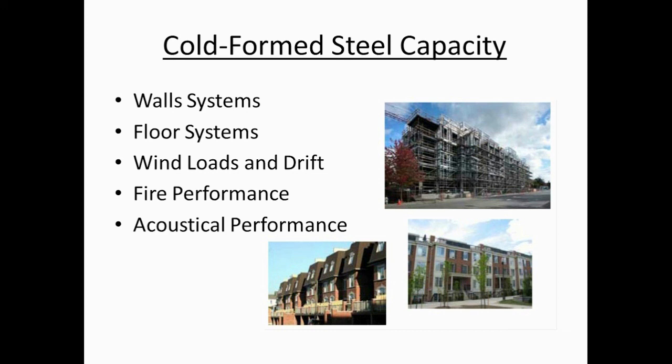I can remember doing load tests on shelf brackets for a movable partition. The framing is steel, but the stud doesn't go from track to track. It stops at the top and the bottom and does not complete the trip. But the point of that is we could put 2,500 pounds on a shelf bracket on that stud, and it would not destroy the wall. And we would jokingly say, I could hang a Volkswagen off this shelf bracket. And admittedly, it was a 1973 Volkswagen, not the current Beetle. But the point is, there was a lot of underutilized capacity that we weren't using.